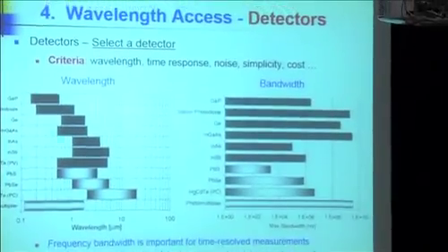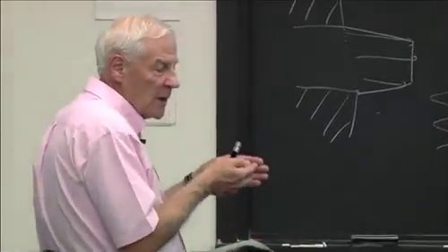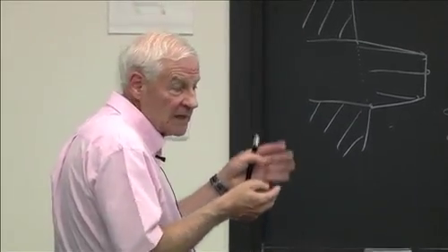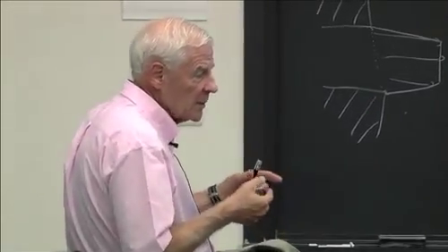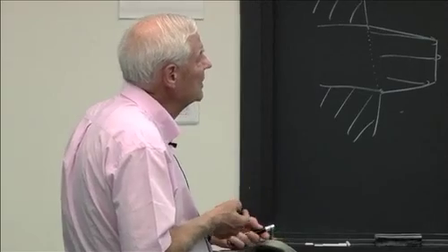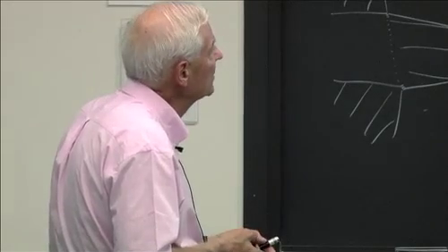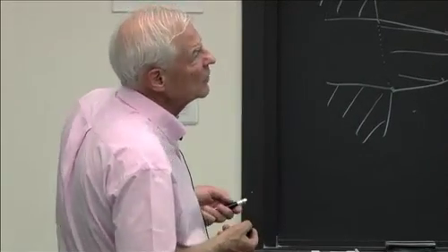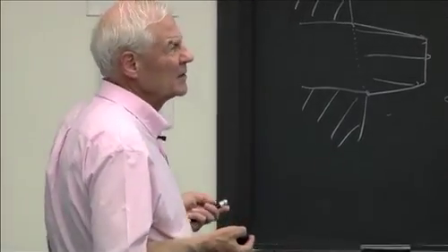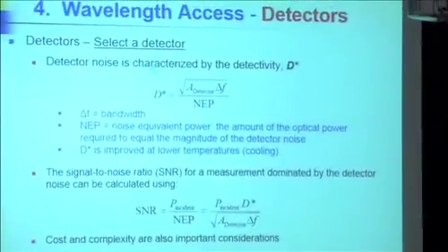So you care about their responsivity at your wavelengths. Here's our mercury cadmium telluride. You also care about the bandwidth. You say, I need 10 kilohertz or 100 kilohertz or megahertz, or you're going to respond to an individual pulse of light that's 10 nanoseconds long. You have to have a very fast detector. That has to be made differently than a slow detector, and that may affect the size. So there are some trade-offs in detectors. The materials, the geometry, and the bandwidth have to be considered. Most of the stuff we do is with CW lasers, and therefore we are typically satisfied with 1 megahertz bandwidth.